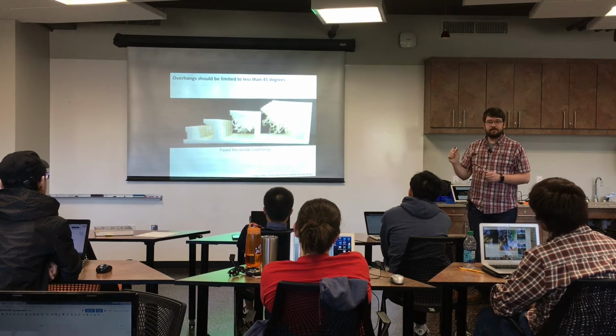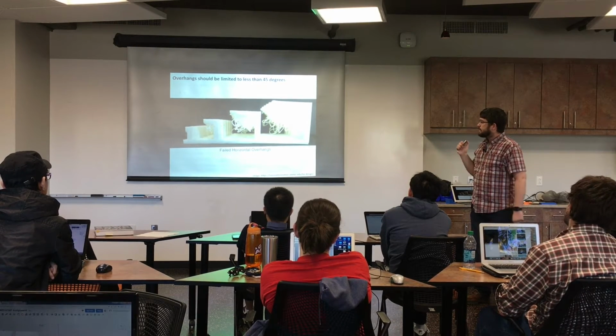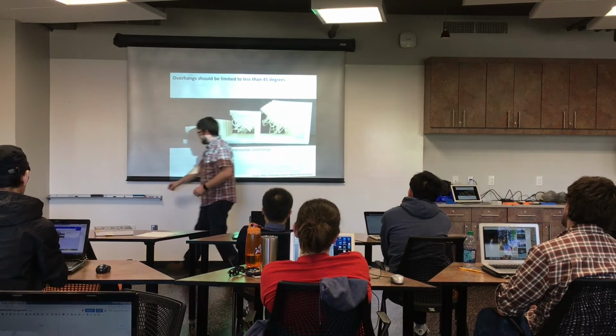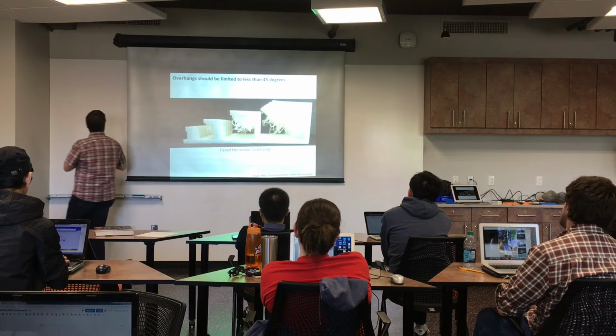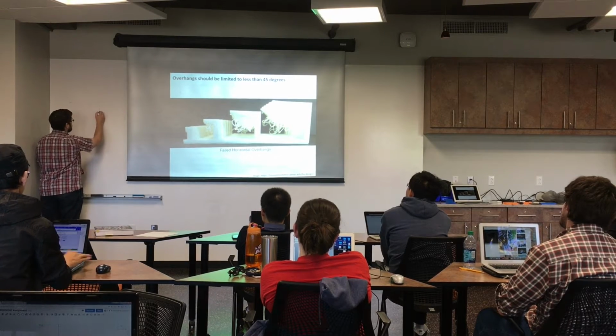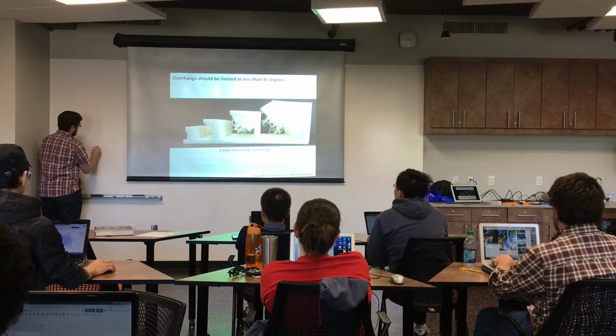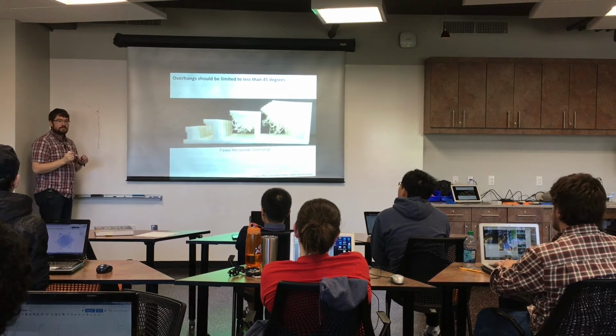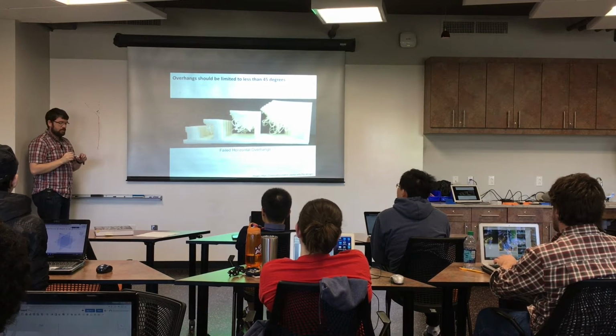So does that make sense to everybody? See why you don't want to do it? So the angle I'm talking about when you're designing your part that you need to watch out for is any overhang that is greater than 45 degrees from there, you should support. It won't make it.